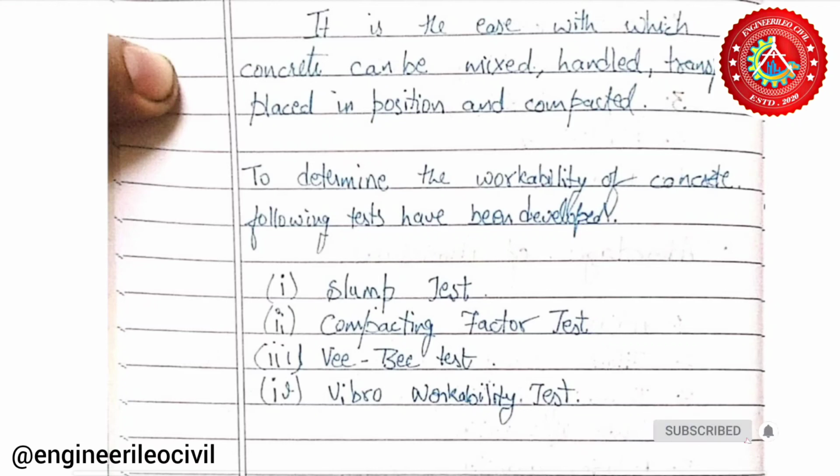Before that, we're going to learn that the vertical settlement is measured as slump in millimeters, and I'm going to tell you the different types of work and their slump results. Like if we test concrete for road work, the slump might be 20 to 30 mm. For vibrated concretes, it is 12 to 25 mm. For mass concrete, it is 25 to 50 mm. And for columns and retaining walls in thin vertical sections, it may go to 75 to 100 mm also.